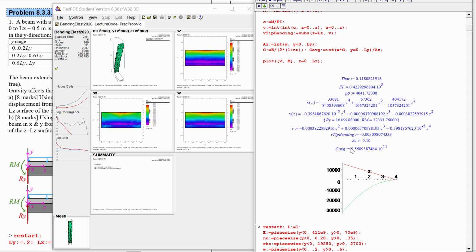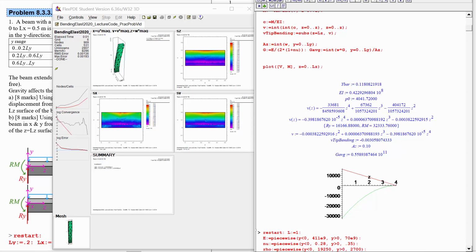Yeah. And we need that to find out what the shear stress is. So from the V that we discovered, we can say that tau ZY would be equal to negative V, because V was sort of directed pointing down, so it would match up with the moment we were applying in the right direction. So negative V over that cross-sectional area. And then we can figure out what the shear strain is by taking tau ZY.